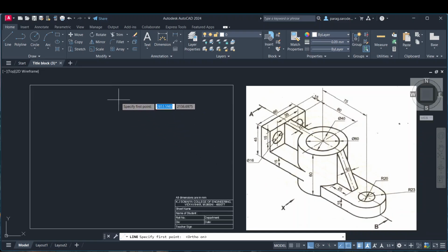For the paper space, we can easily see that the side view always lies on the left or right of the front view, based on whichever side view is asked. So in the given figure, we can draw the sectional front view, top view, and the right hand side view. The right hand side view should lie on the left of the front view.